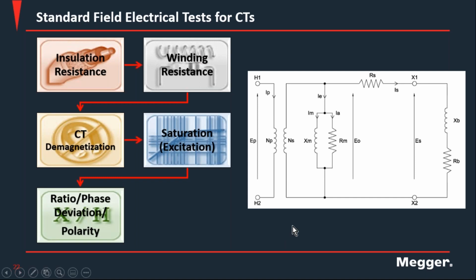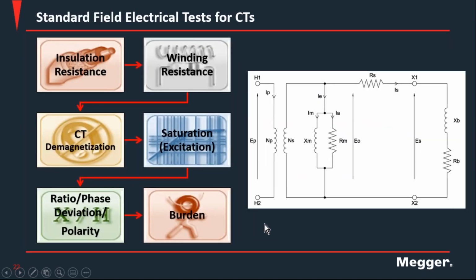Then the next phase in the test is demagnetization, to take care of that probable remnant flux in the core and to make sure that the subsequent measurements, all AC based, are not affected by it. So again, certainly a possibility. That's why it's recommended to run these two first and then go to demagnetization to continue running your other tests.